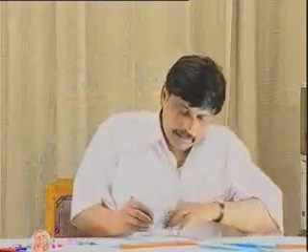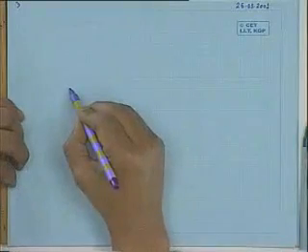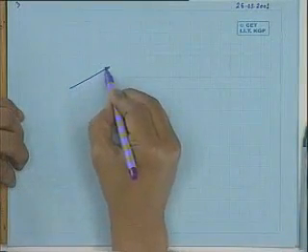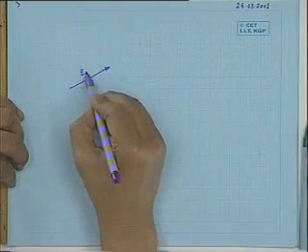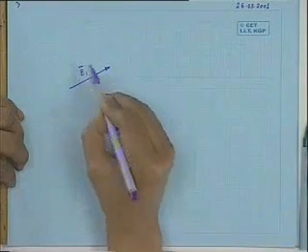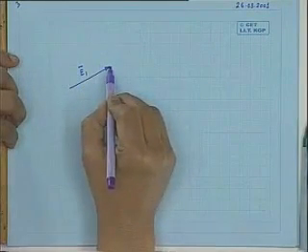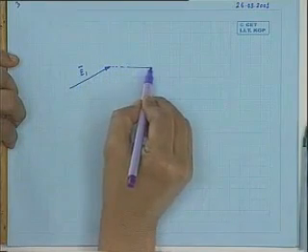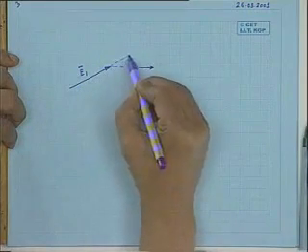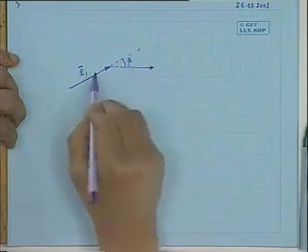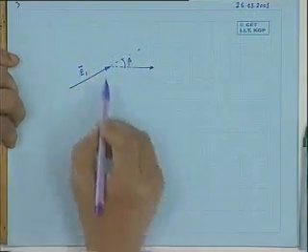Therefore, you have to add three phasors whose lengths are equal and which are displaced by angle beta. Suppose I call this phasor E1, the voltage in coil 1. The voltage in coil 2, E2 bar, has equal length but lags this voltage by an angle beta.